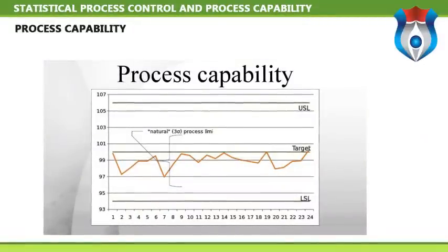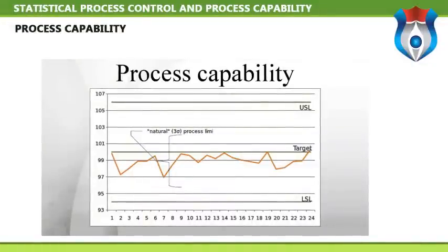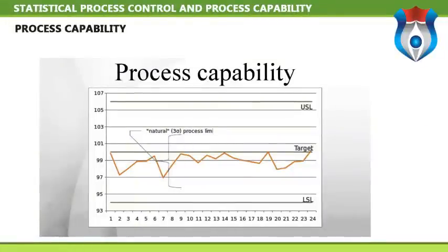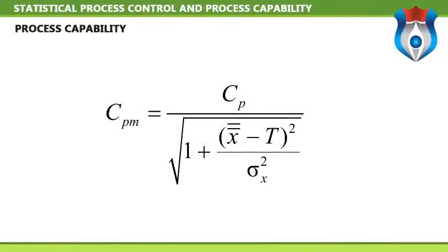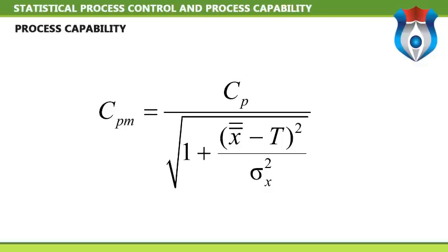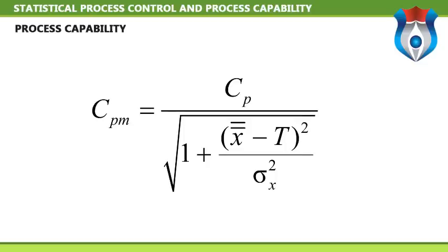Process control refers only to the voice of the process, looking at the process using an agreed performance measure to see whether the process forms a stable distribution over time. Process capability measures the goodness of a process, comparing the voice of the process with the voice of the customer. The voice of the customer here is the specification range, tolerance, and/or the nearest customer specification limit.